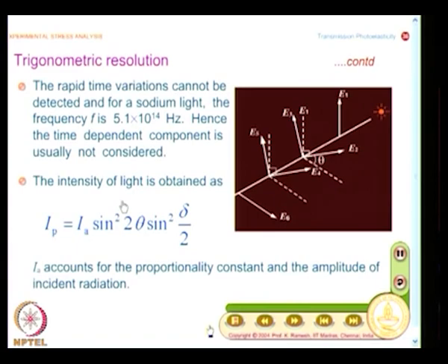When theta goes to 0, it essentially means the polarizer axis coincides with the principal stress direction at the point of interest. When it coincides, only one light beam travels through the thickness of the model, and that is completely cut off, and this is independent of wavelength.